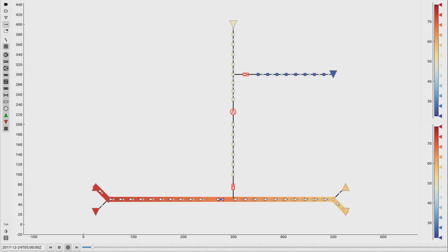The last important thing to know about this example is the fact that the top exit can only withdraw gas at a minimum pressure level of 55 bar, so the network control will have to ensure that this requirement is fulfilled. When we start our animation now, we will see the network state evolving over time. The control of the active elements is optimized to fulfill the demands while changing as little as possible. Let's start our animation and see what the solution looks like for this scenario.